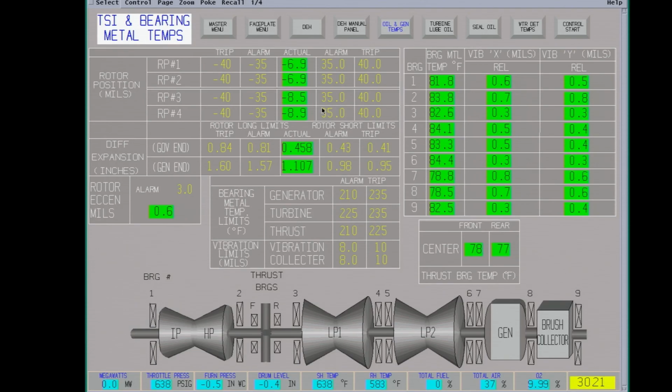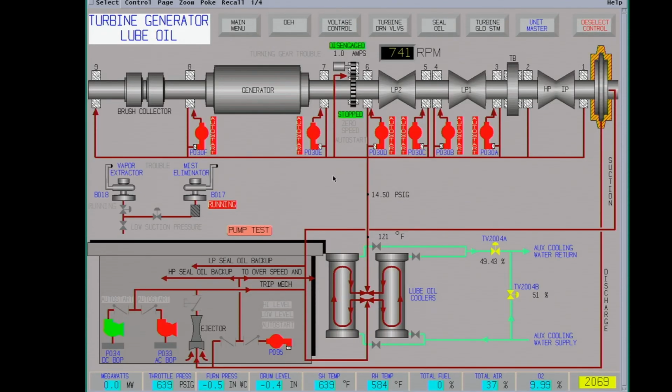This screen here is pretty important. We have this up on the other board. This is monitored all the time. You have relative X vibration and relative Y vibration of the shaft. Big thing is want to make sure the 86 relay is reset or you won't get very far with this. There's one item that gets forgotten.